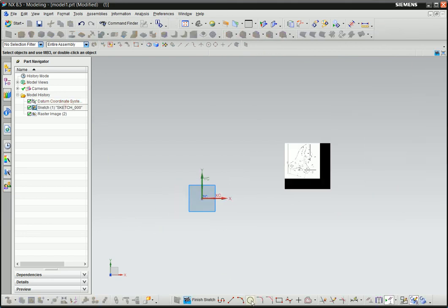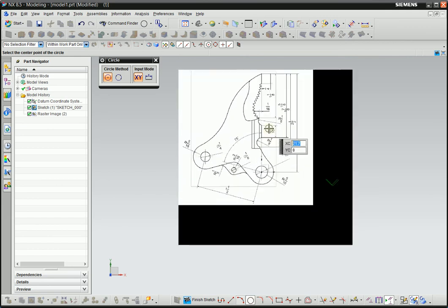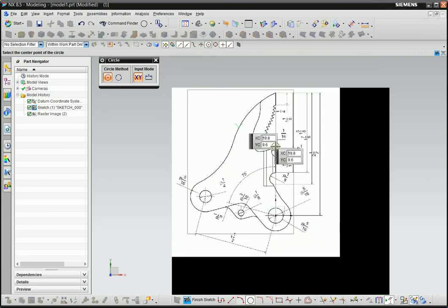If you look at this shape, first, if you want to extrude, you need to close the loop, close the curve. So we want to extrude this big piece first, and then the teeth and this little ear. Lastly, cut into that.